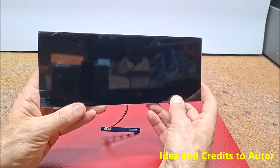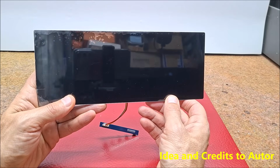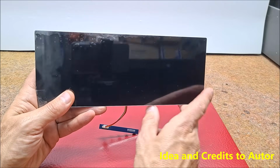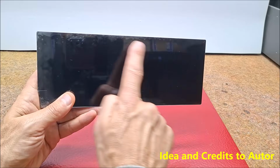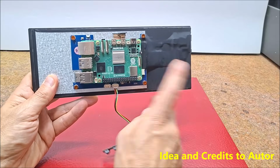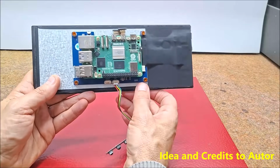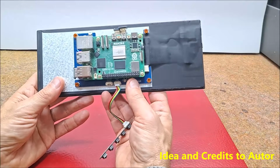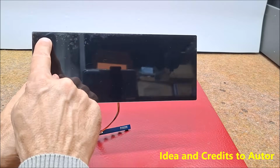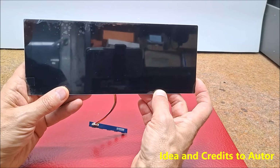The original device is based on a 7.9-inch ultra-wide HDMI touch display with a resolution of 1280 by 480 and a Raspberry Pi small single-board computer. I currently have an ultra-wide LCD with a built-in Raspberry Pi 5 intended for a post-system project, so I decided to use this existing hardware. The difference with the original project is in the resolution and dimensions of the display, namely my display is 9.3 inches and has a native resolution of 1600 by 600 pixels.